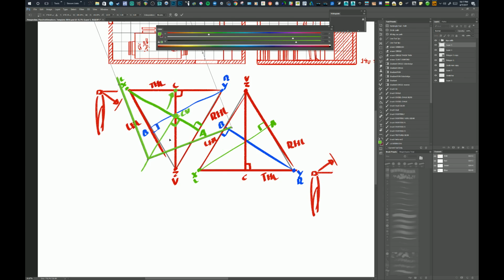So what I do is I'm reverse engineering the station point. The difference between 1 and 2 and 3-point perspective is that 3-point perspective has a predetermined distance at which you place the station point, whereas in 1 and 2 you can place it anywhere along the distance line and then calculate your left and right vanishing points.